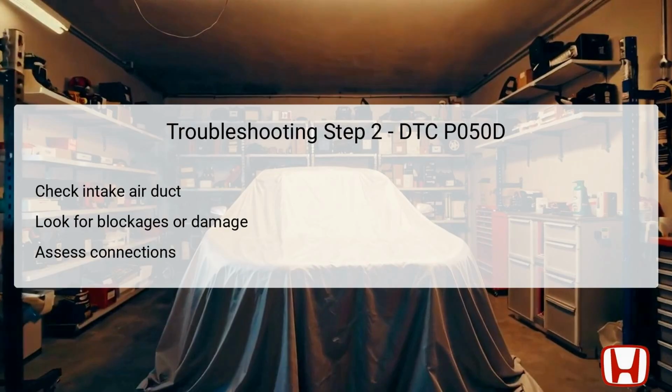If the duct is found to be in good condition, the technician can move on to the next step in the troubleshooting process. However, if any issues are discovered, reconnect or repair the intake air duct, or replace it entirely if necessary to ensure optimal airflow to the engine.